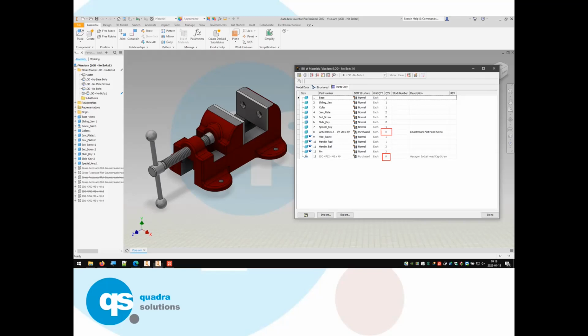You can hide on the parts list. You do it manually, or use a bit of iLogic. You can find all the quantity 0 rows in the parts list and set the visibility to off. You could, in the bill of materials, maybe change it to a reference component. A reference component doesn't show up on the BOM. A little bit of jiggery pokery there.